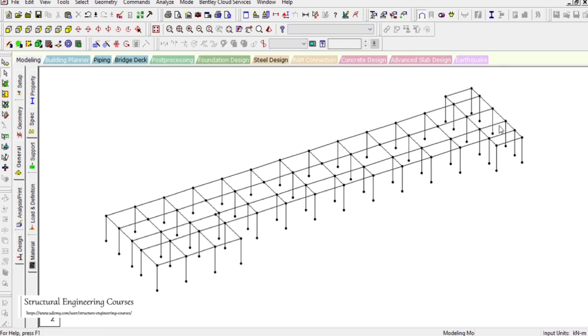And for the ramp, as I had discussed with you earlier, I shall not be modeling the ramp here, but to make sure that the ramp loading is considered, we can provide a full floor slab here and then apply the loads so that the columns and the foundation are designed accordingly. But if you want to do a fine-tuning exercise, or if you have sufficient time, you can provide cantilever beams on all the columns along the ramp profile.